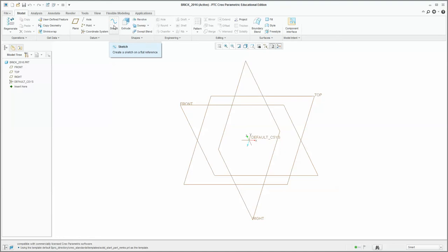Sketching is for our drawing on a flat surface. Extruding takes our 2D shape and extrudes it into a 3D pattern, which we'll be looking at shortly. Revolve looks, as you see, a little bit of a donut tool. Take one pattern, you can rotate it in 360-degree angles. Sweeping tool creates vases. You can take a basic part and extrude on the vertical. And the sweep blend tool is not something we're going to use, but as you can tell from the pattern, it does a fairly similar function to the other two. Patterns we don't use in this particular course interface.